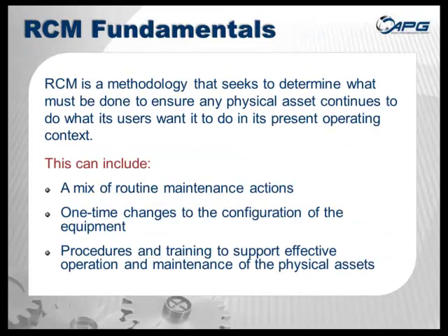The fundamentals of RCM, again based quite closely on the principles of SAE JA1011 and 1012, is that RCM is a methodology, a tool, a technique. It's performed to determine what must be done to ensure any physical asset continues to do what its users want it to do. Based on how it's being operated today, you change those operating parameters, a lot of times the requirements change, and hence so must the actual tasks to support them. Fundamentally, the output I like to categorize into a few boxes.